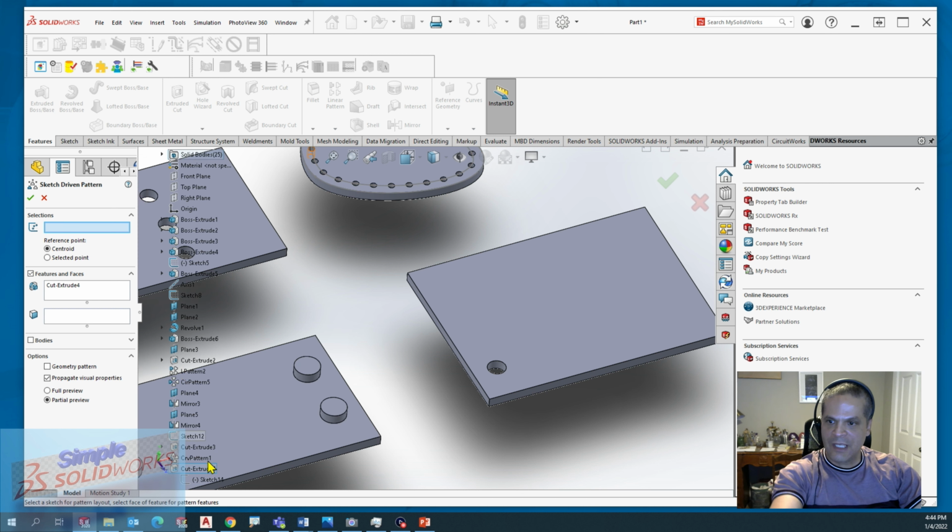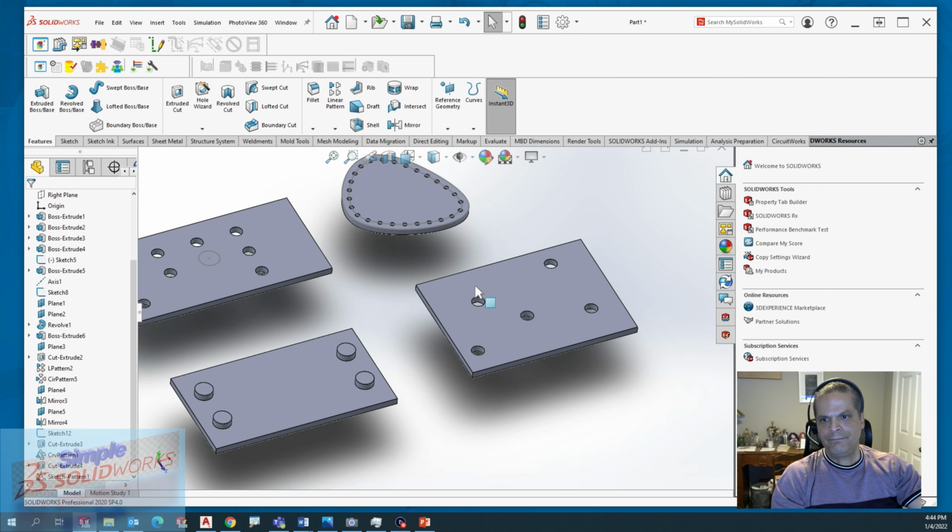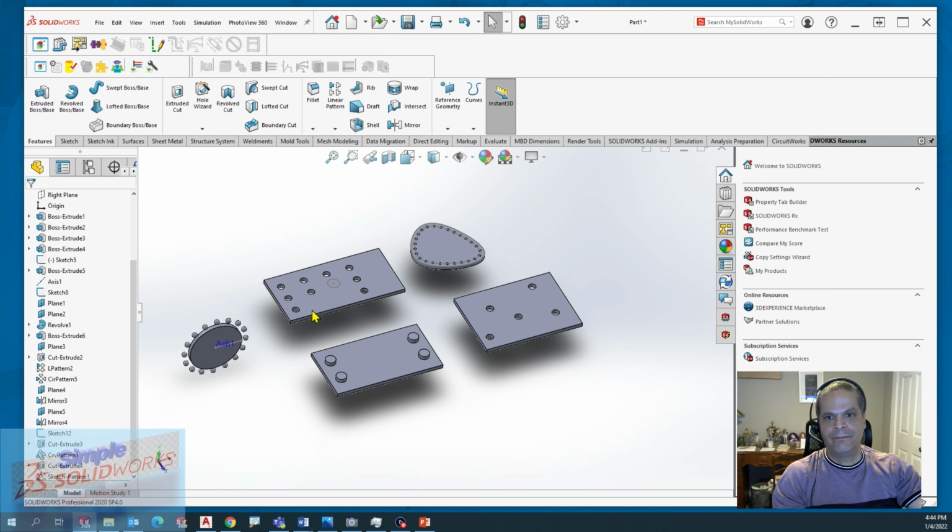And once you dig for the sketch on the model tree on this side, and you click on that sketch that you made, it's going to put those patterns into those specific dimensions that you have. This is good if you have that type of shop that needs to have these dots laid out all over the place, or these holes made with machining and proper ordinate dimensions. So this is very helpful. And once you have your pattern done that way, you confirm it, and voila, you have your holes. So these patterns, you can manipulate them however you need.